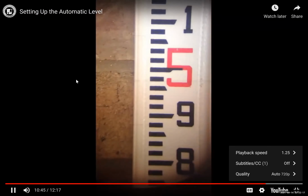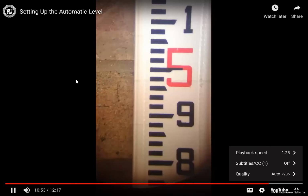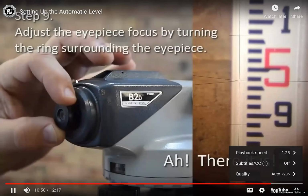Often the crosshair may not be visible at your first look. The crosshair isn't broken or missing, it's merely out of focus. Rotate the eyepiece until the crosshair comes into its sharpest focus.